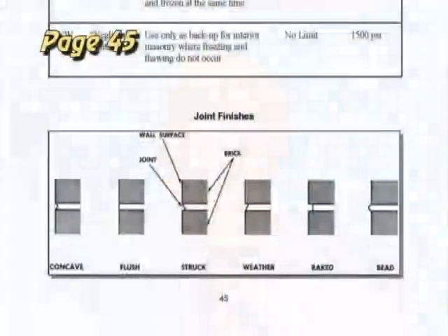If you're working in an area where you're subject to a lot of frost and freezing, and you're putting up exterior brick, you will most likely want to use SW brick. Read through that chart, understand what the chart is trying to give you. Of a little bit of interest is the joint finishes. I've always been fascinated by that. Quickly look through that.